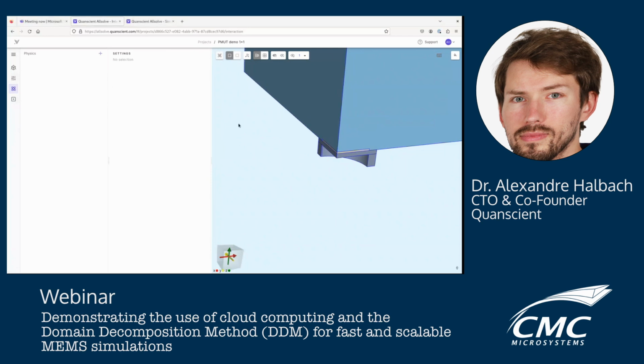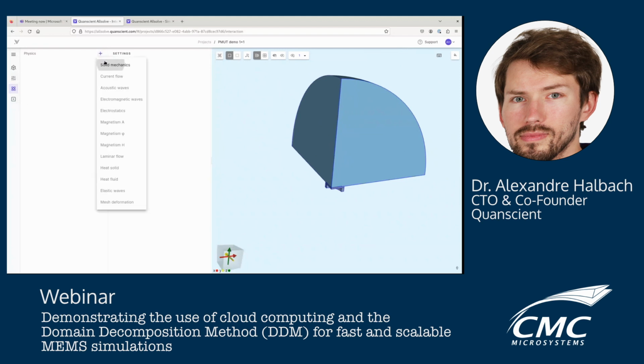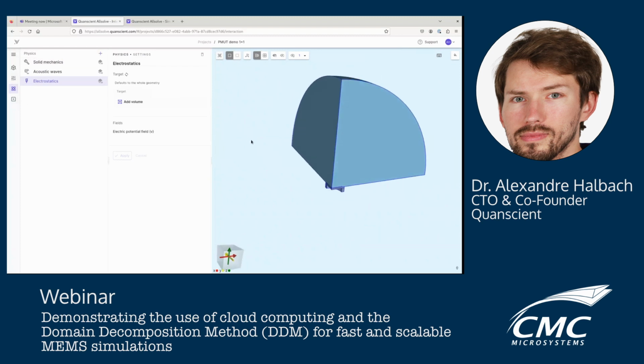In the physics setup, here it's a three-physics strongly coupled simulation. So we're going to have solid mechanics, we're going to have acoustics, acoustic waves, and we're going to have electrostatic simulation. You could, of course, do current flow as well, but typically electrostatic works well, and you can also get the number of charges, capacitance, whatnot there. I won't show that, but you have lots of options, such as if you have large displacement or if you have pre-stress, you can include this all here quite trivially, which is pretty critical because it's always the case due to fabrication. Next step is to set up the physics.